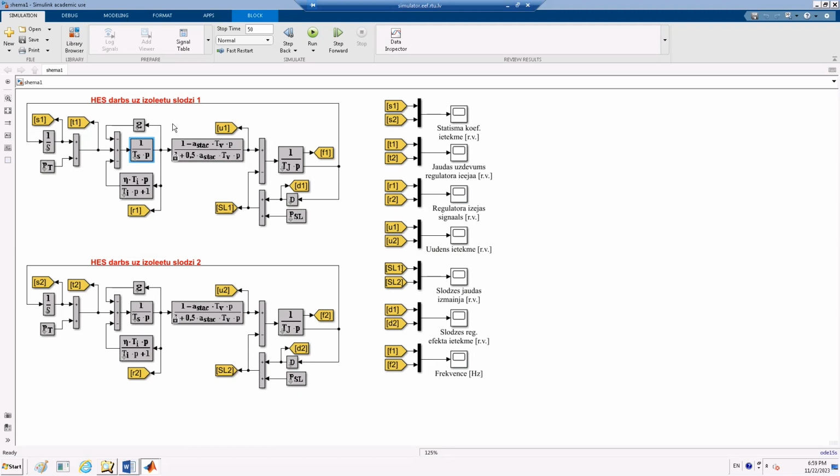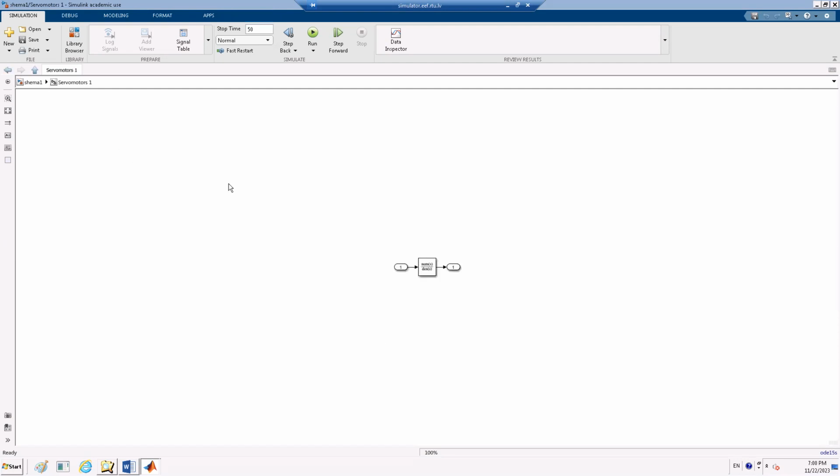We give a signal to open more or to close. The signal goes to an electrical motor that opens and closes. So we have an electrical motor unit, and every electrical motor has an inertia and time delay for response, as you understand. In this case, this unit represents this valve reaction, and it is how it's made.